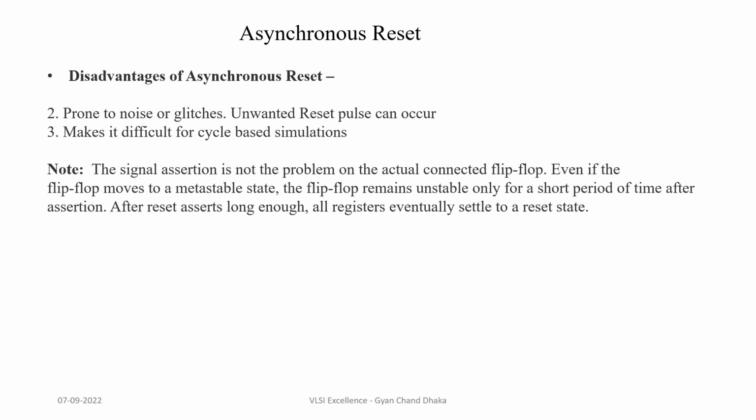Now, one thing to remember here is the signal assertion. As I said, signal assertion is not a problem on the connected flip-flops. Even if the flip-flops move to a metastable state, they remain unstable only for a short period of time after assertion. After reset asserts long enough, all registers eventually settle to the reset state, because the reset is applied for quite some time. So asynchronous reset assertion is never a problem. The problem only lies with asynchronous reset de-assertion.